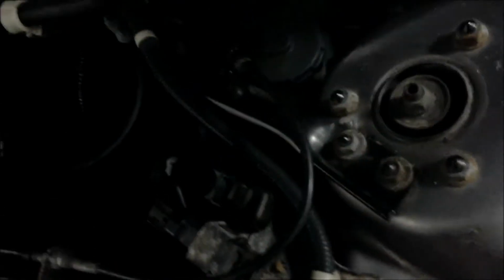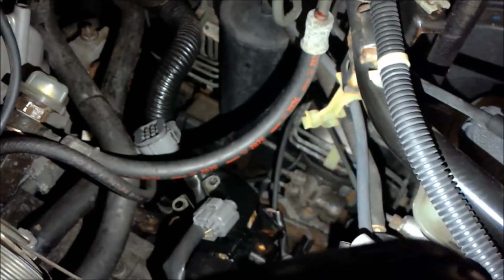Alright, so that drive-by cable is going to be right here. So you've got your throttle body right here. You've got the throttle cables all right here. So these will be pulled to open up the throttle directly by the driver. And then this is also going to be a returnless fuel system. You can tell by just this one fuel line with the red lettering on it. So if you only have one that goes back to the fuel tank, it's a returnless. And if you've got two going back to the fuel tank, it's a return fuel system.